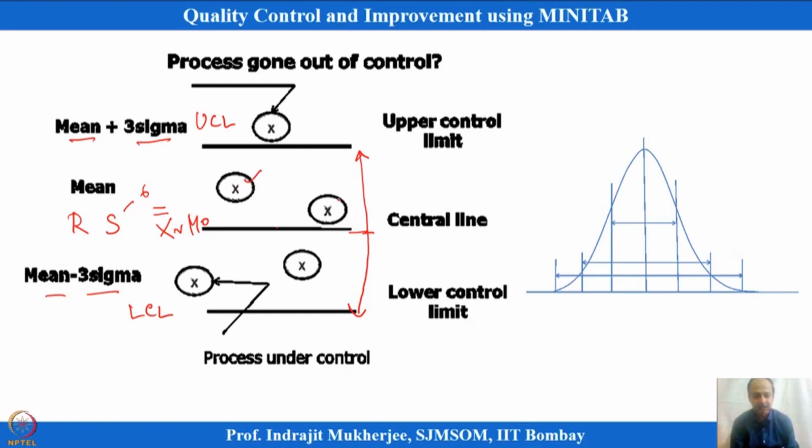That is why this is one observation falling within this, this is one observation, all are falling within this. So, there is no abnormality going on in the process. This is at time point, let us say, T1, this is at time point T2, this may be at T3, where I have taken an observation or average observation like that, this may be T4 and this may be at T5. What we observe is that at T1 it is within limit, so no abnormalities. At T2 also no abnormalities, because it falls within this plus or minus 3 standard deviation.